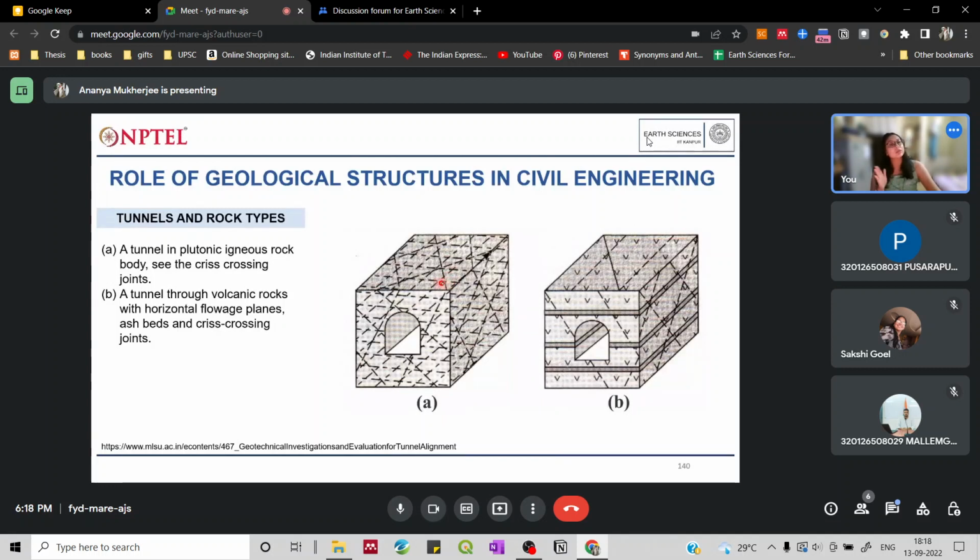Limestone, though it is compact, owing to its chemical composition and the characteristic that it has, can dissolve very easily with continued interaction with water. You will have caving. So there is something called caving that is related to limestone areas. If you have limestone, it will cause caving, and then you will have a very weakly supported tunnel structure there. It is not suitable.